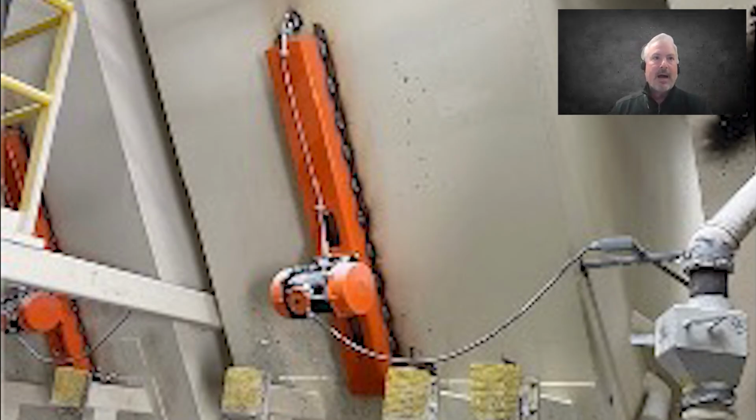Here's a glass cullet hopper. The very irregular shape of the material would cause the material to bridge over the discharge. We installed the electric vibrator to operate when the flow detector indicated a low flow situation. There's the model that we use on our channel with the safety cable kit. Here's a wrap bin in an asphalt plant.